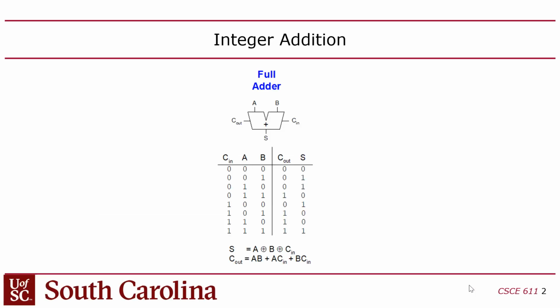Let's talk a minute about adders. Did you cover adders in 211? Yes. Okay, so you remember you had a full adder, which is basically a 1-bit adder. A 1-bit adder had 3 inputs and 2 outputs, because there was A and B, which are the 2 bits, and then there was a carry in from the previous column, from the adder to its right.